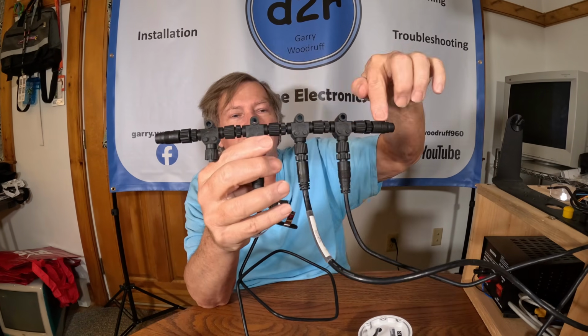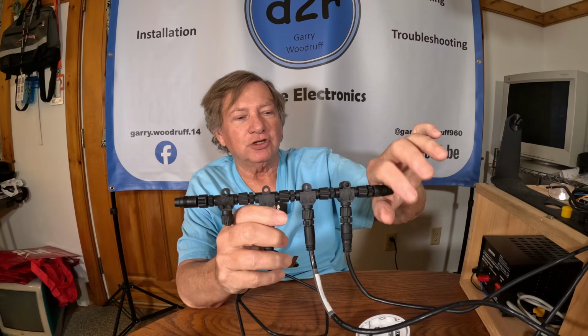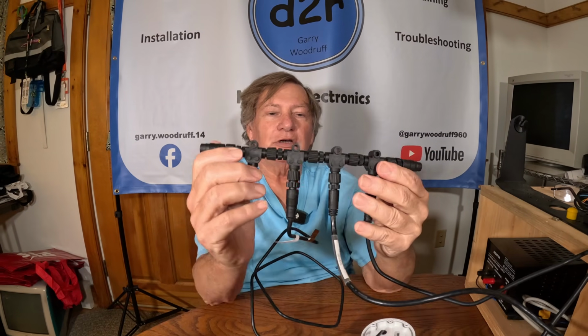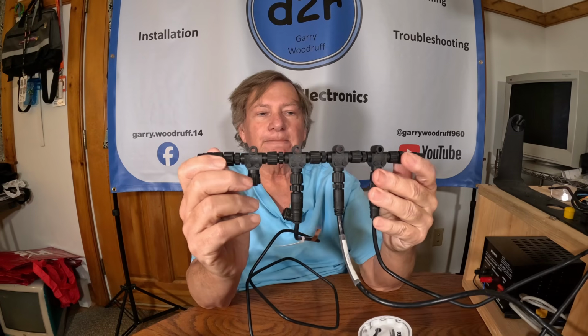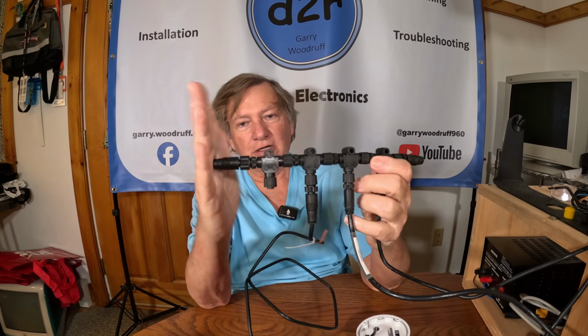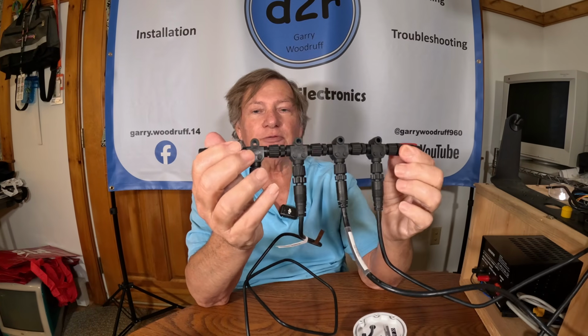This piece back here is what's called your backbone. Okay, so the backbone has a terminating resistor on both ends. So this is electrically what's called a balanced network, a balanced resistance network, okay? So in your boat, you should have at one end of your network a terminator resistor, and at the other end of the network, you should also have a terminator resistor.